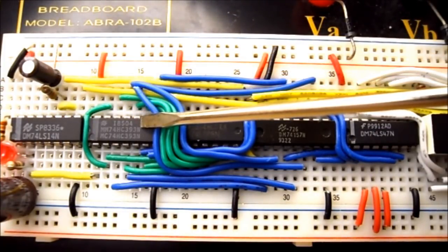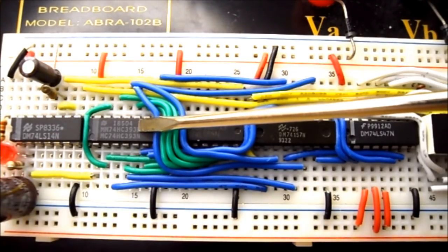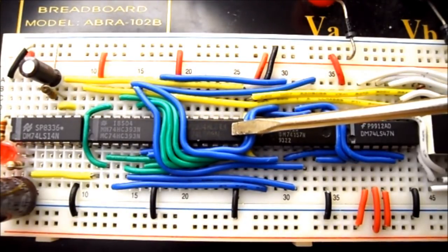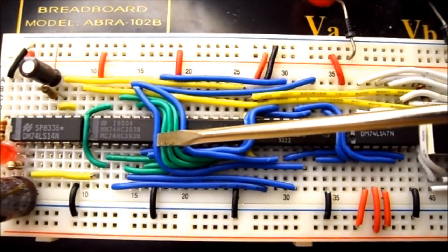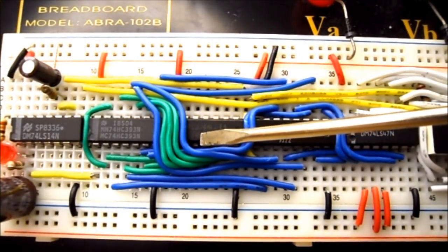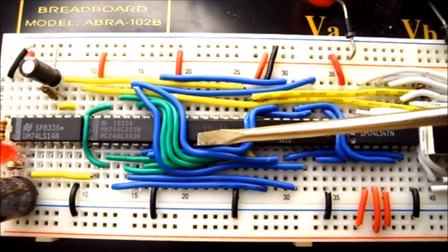The next IC is the 393, and that's a binary counter, a dual binary counter. So one is being used to count from 0 to 9, the other one counts 0 to 5. The next IC down is my 7408, which is the AND gate, which I use to decode the output from the 393 and reset it when it gets to 9, or reset it when it gets to 5. So the reset line is actually going on the 10 count or the 6 count.